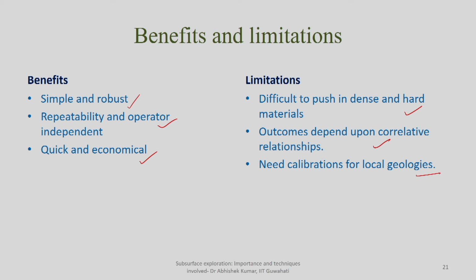And it needs calibration for local geology. That will also indicate the tentative range of pressures you will be dealing with once you push your dilatometer at the site of interest.